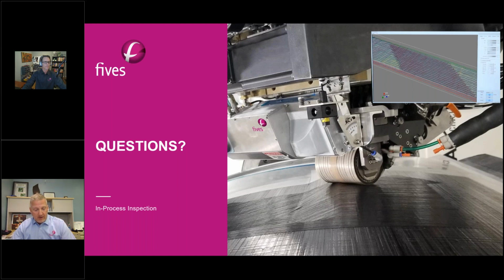Okay, excellent. Next question, what is the maximum number of plies or total uncured composite thickness that OCT can scan? So it does it on a ply-by-ply basis. So the amount of plies doesn't matter. The overall thickness doesn't matter because I measure as I lay. So each layer of 7.5 thousandths thick, we are collecting data. That data then is stored, and we can tell through the layers where all of the, let's say, overlaps, the gaps, anything, all of the data is collected and we know in a particular region. So it scans as we lay each individual layer. So the overall thickness of the part doesn't matter to us. Okay, great. Does carbon fiber dust affect the laser?